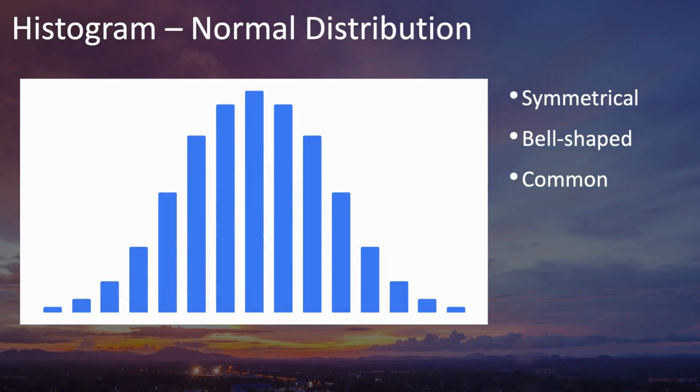This histogram has a characteristic bell shape known as the normal distribution. The normal distribution isn't what you normally see for all processes, but it's a nicely shaped symmetrical distribution that is common in many situations. And it lends itself well to some of the more basic statistical process control methods. Different shapes of distributions can mean different things, and sometimes it's natural for that process and sometimes it's not.